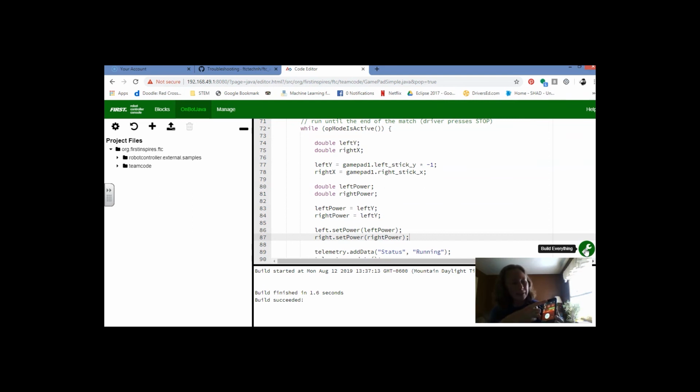I also can see I've got a little gamepad icon up there that shows user 1. If you don't see that gamepad icon, just make sure your gamepad's connected, and you may need to hit Start and A at the same time to activate this gamepad and set it as gamepad 1. Start and A. Next, I've got the software loaded. I'll hit init. After you've hit init, your servo is going to go to its initial position. So check your robot and make sure the servo is where you want it to be. I wanted mine to be pointing straight up, and it is, so that's helpful. Next, you can hit play, and you can try to drive your robot. I'll show you what that looks like when I test it.